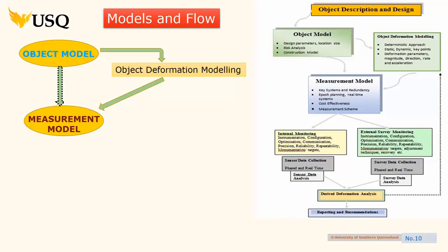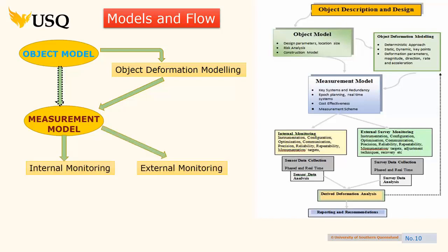When you know that, you get a measurement model. So you actually can put down and say, and we usually use what they call FEM, finite element analysis, for the model. And then you know what should move. In other words, we expect the bridge to sway in 100 km/h wind by so much. Yeah, in the middle, near the edges, up and down maybe, right? And in the long term, if there's subsidence of the ground, we would expect this would be the impact. So that's mostly the engineers who would come into that.